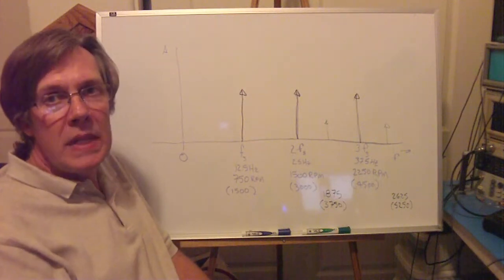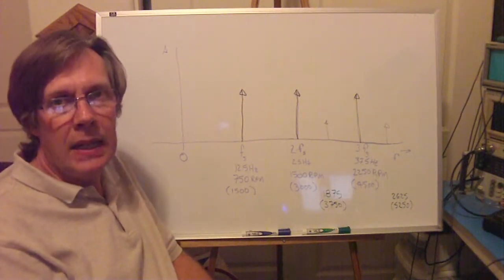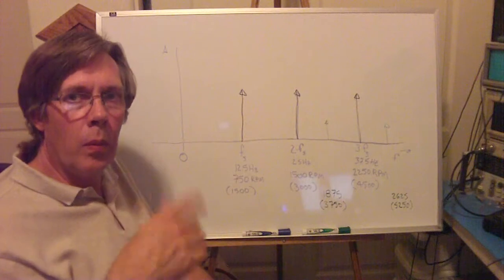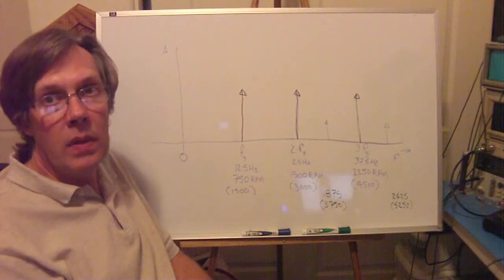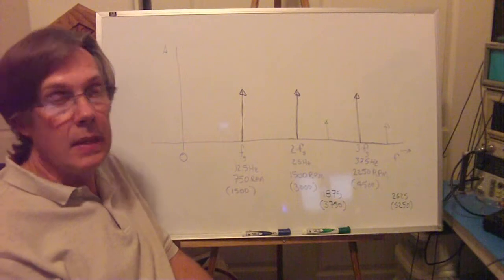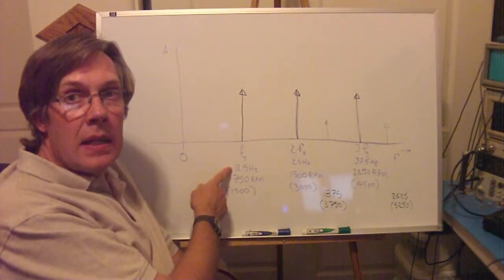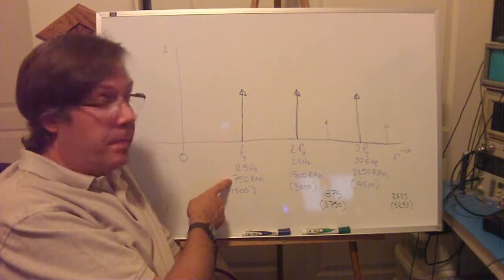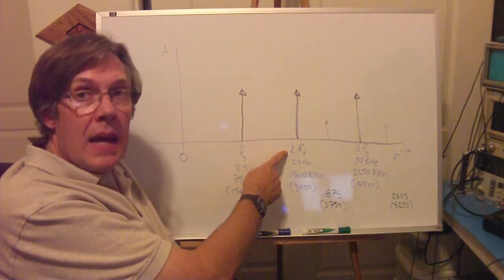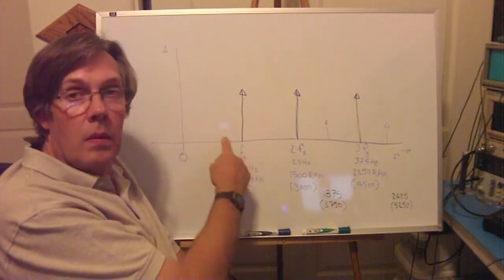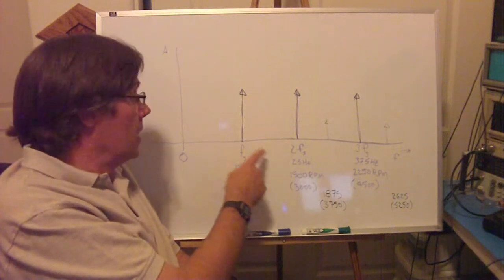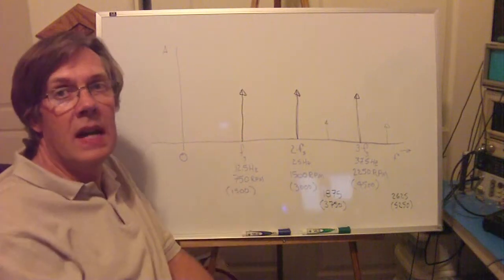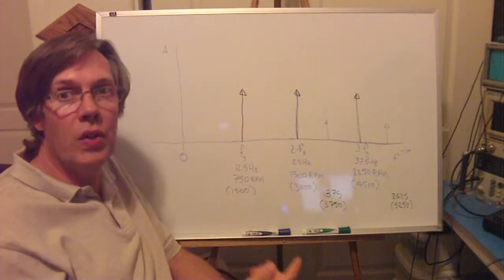As we mentioned before, our strobe is set up to sample at 12.5 times per second, 12.5 hertz. And any time that the blade is rotating in synchrony with that, it'll look like it's standing still. Well, what's that mean? If we're sampling at 12.5 hertz, we multiply that by 60, that corresponds to 750 RPM. And 2 times that, then, would be 1,500 RPM. So in this case, if the blade is turning at 750 RPM exactly, and we're sampling at exactly 12.5 hertz, it'll look like it's standing still because it's 1 full rotation per sample.